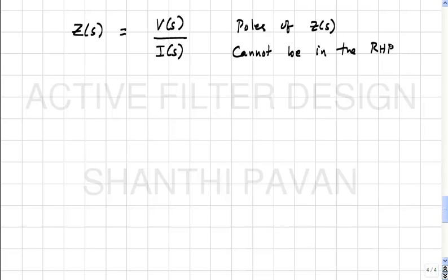Of course, if you don't know how to prove it, you just say that an inductor, for example, goes to infinity at omega equal to infinity. So S equal to plus infinity is a pole of the impedance function of an inductor, correct? So poles can be on the j omega axis.